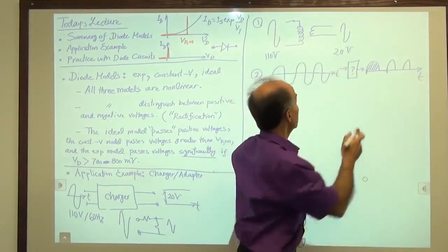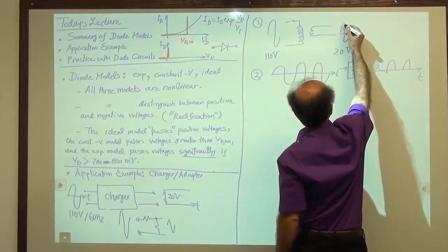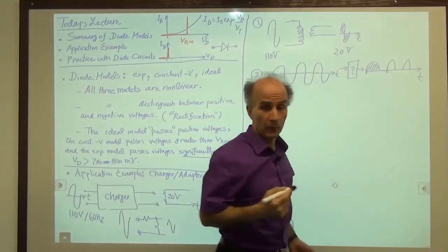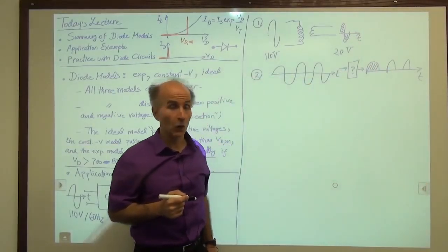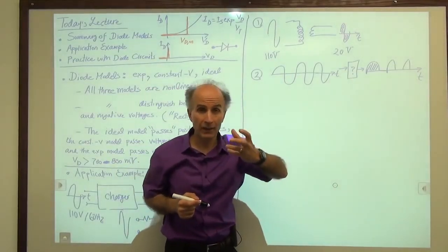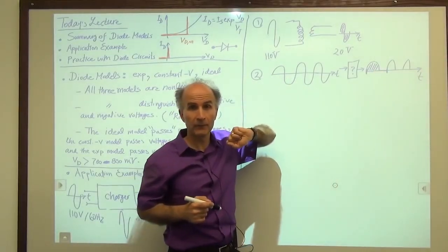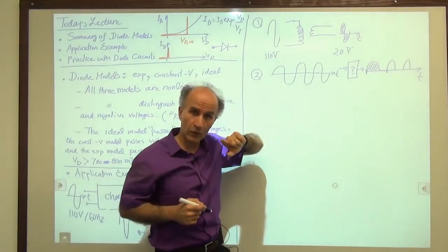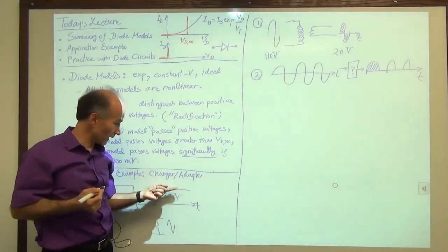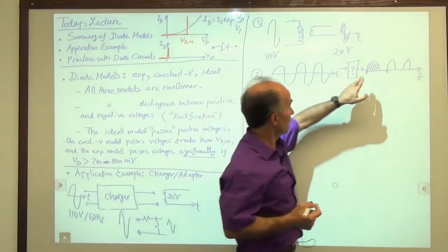For these sinusoids, if you remember from your signals and systems, the average is 0, because if we integrate, find this area and find this area, they cancel each other, and we end up with 0. So when we went through this black box, through this nonlinear operation, magically we created a non-zero average at this output. All right? So that's close to what we want. We want some sort of constant value. Average means DC. So we want some DC. The problem is that in addition to what we want, we also have some other stuff here.